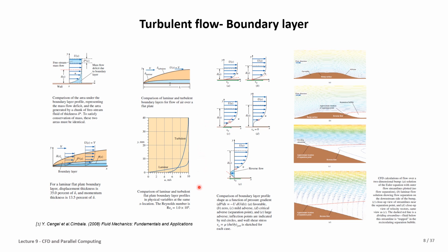As well, when we are considering the boundary layer with different velocity profile and pressure, we have the reverse flow, which makes it possible to find the separation point, and one of the applications of the separation point is to understand the drag force. We will see it in the next slide.